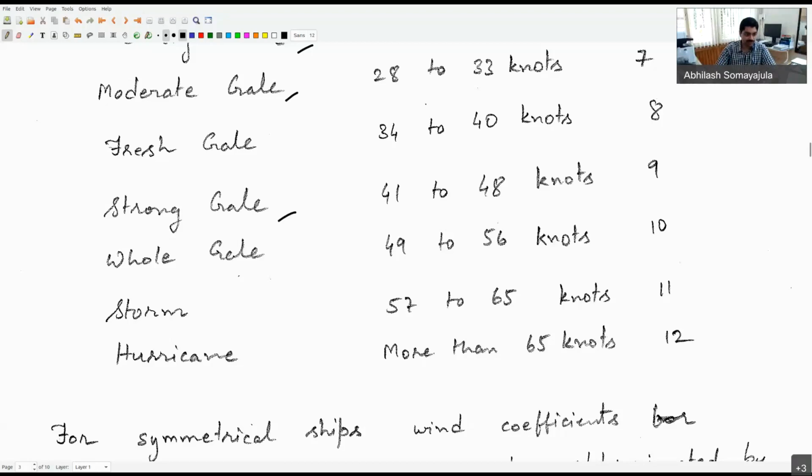And one such strong wind is what wedged the Ever Given ship into the Suez Canal. Remember the incident from last year where a huge container ship got wedged inside the Suez Canal. Now they are planning to expand the width of the channel, given the debacle that happened last time. So when you have huge wind speeds and a large superstructure area, it becomes really important to consider those wind forces, because they can be significant in pushing you around, especially along the beam, because you can't compensate for them directly. You don't have any thrusters working to push your ship sideways in a typical ship, right?